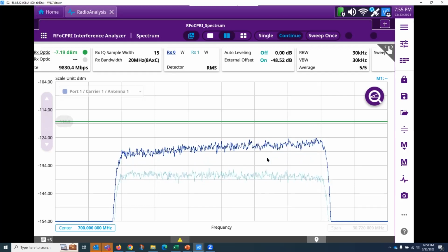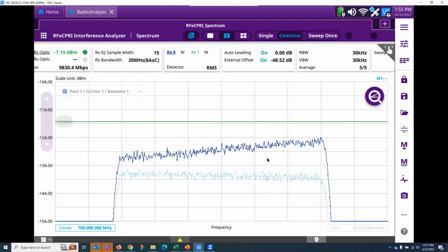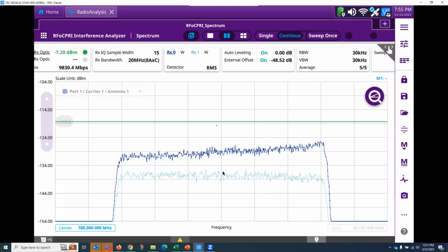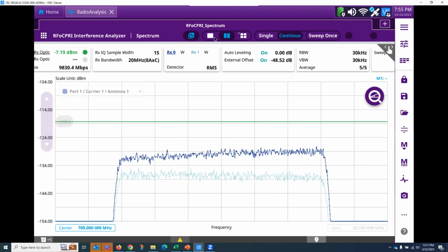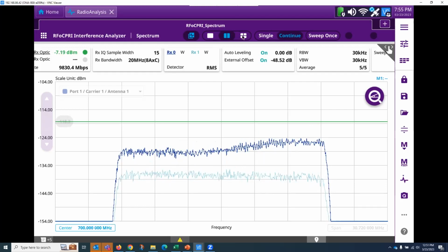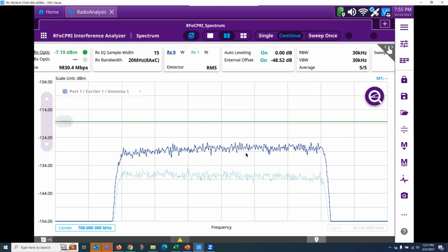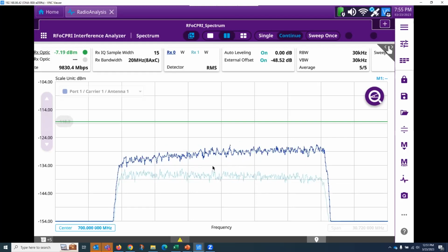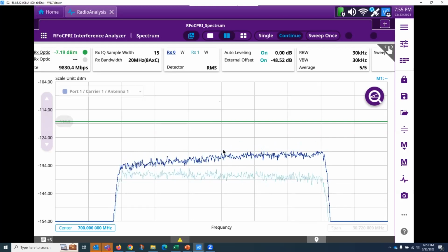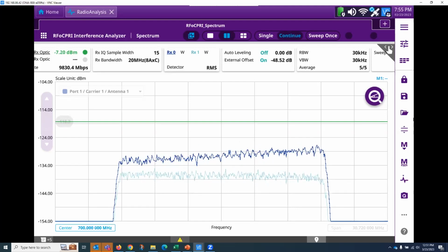My dirty little secret in the background on my little setup is, again, I have an antenna. The reason I have single port PIM is I've loosened my N adapter, which goes from a DIN, because this is a really old setup, to a coupler to an N adapter. I just unscrew it enough that I'm getting a horrible VSWR, if you will. That's how I get single port PIM: I have loads on it and I just unscrewed one of them. So hopefully that answers your question for single port internal versus external.